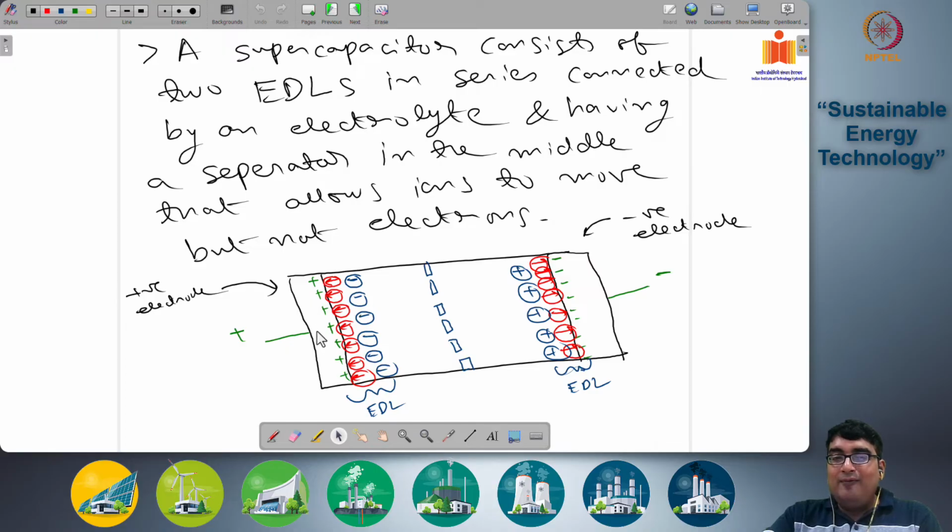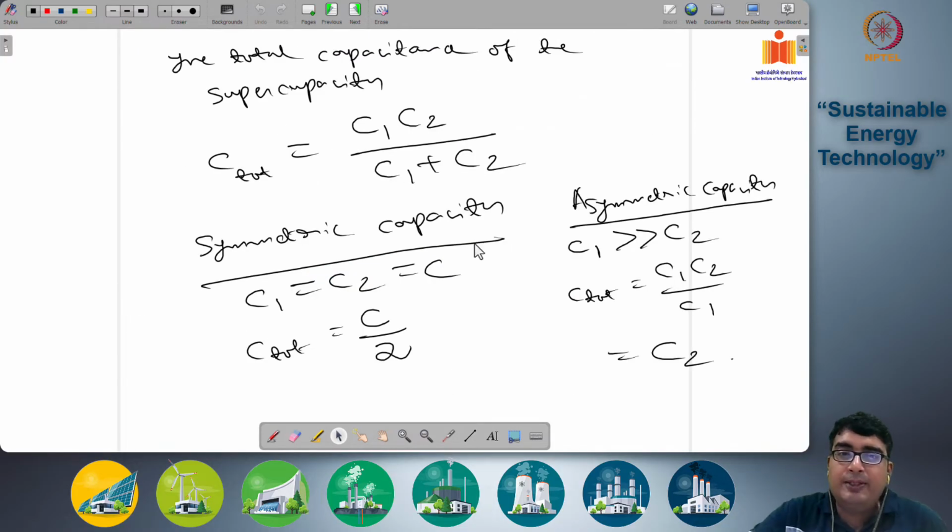Remember, the reason why we have to include both is there are two dielectric materials here, and basically you have two capacitors here: positive charge, negative charge, dielectric, one capacitor; positive charge, negative charge, dielectric, second capacitor. This is forming because you have two metal plates and the local capacitance is happening in the proximity of these plates itself. Okay, you don't have one double layer of charge separated by a dielectric, you have two double layers of charge and you have to account for them both.